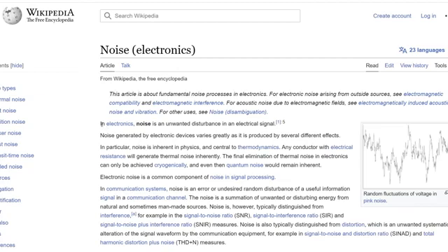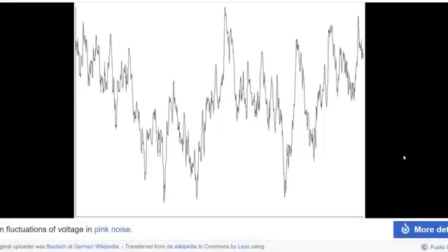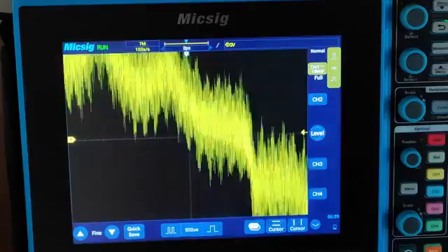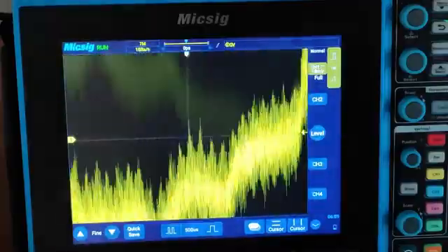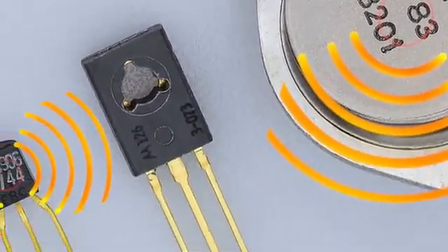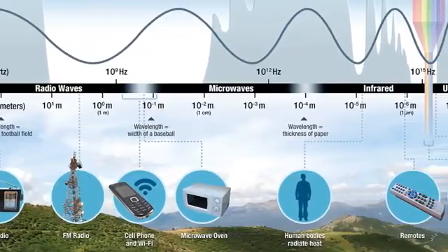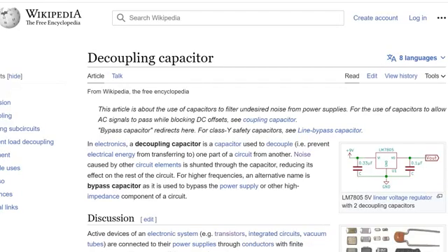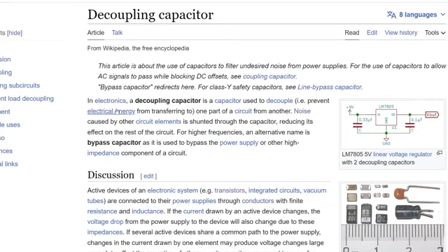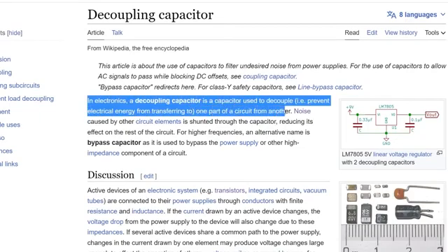In electronics, different parts of a circuit can create noise or electrical disturbances that can affect the performance of other parts of the circuits. This noise can be caused by various factors such as switching of transistors, voltage spikes, electromagnetic interference, and so on. Decoupling capacitors are used to suppress this noise by providing a low impedance path to ground for high frequency noise.